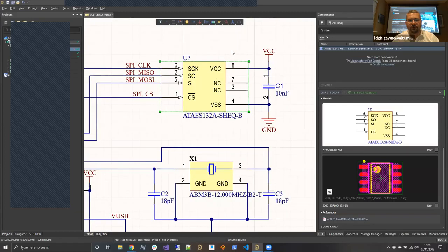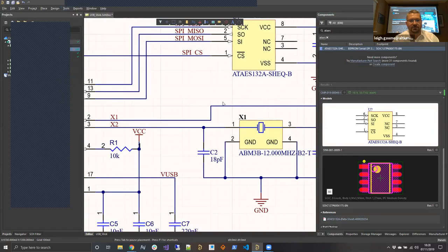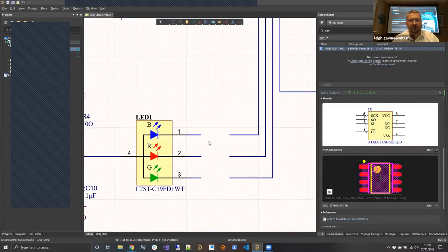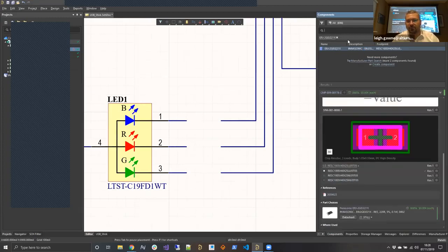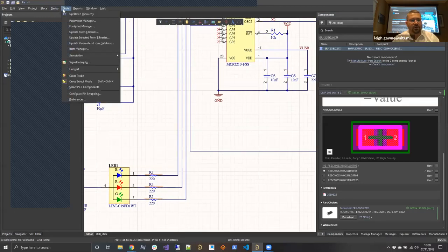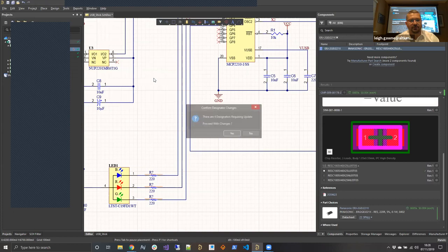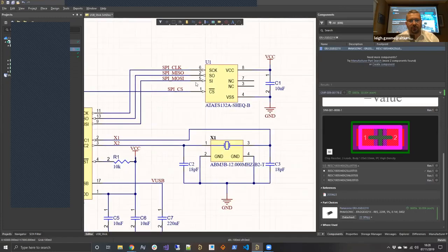And what I'm also going to do is now throw in a couple of resistors. I've got those also missing from the schematic, so we're going to go and pull those as well. Again, I'm going to copy and paste an exact part number to show you how the part number search works. And so here, part number search, again, pretty quick. What I'm going to do is just paste these into the design, as you can see. And we have our completed schematic at this point. So I'm just going to real quick go in and annotate the schematic. And there we have it. So we're in pretty good shape.